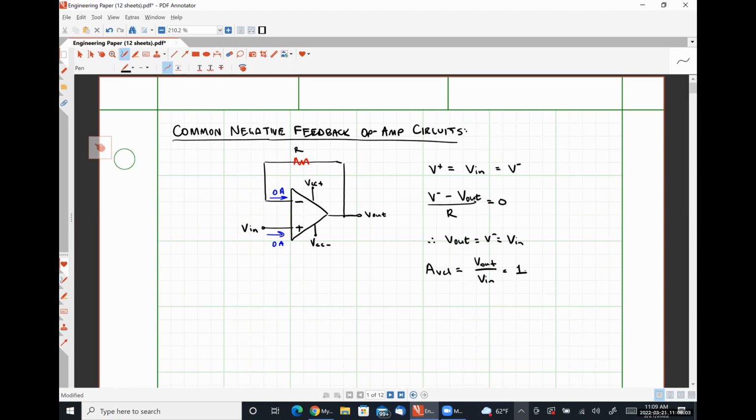So you would just amplify the voltage signal using a unity gain buffer so that any necessary current to deliver power to the output load would come from the power supply itself instead of the sensor in question. So again, this guy is called a unity gain buffer.